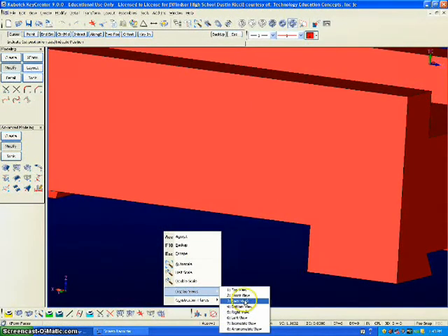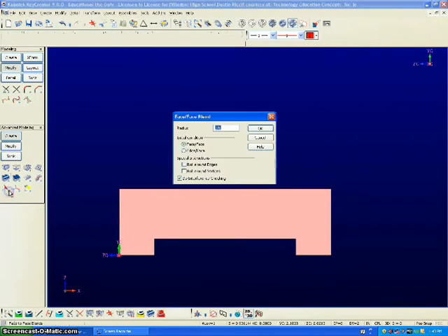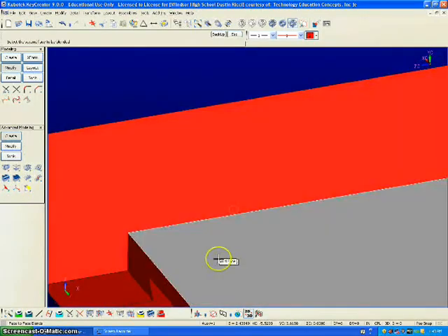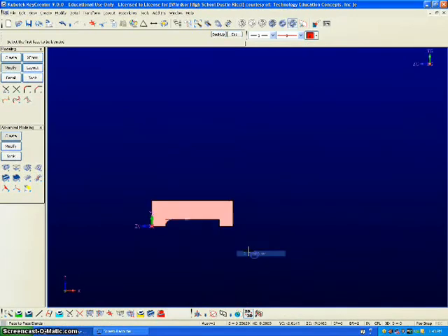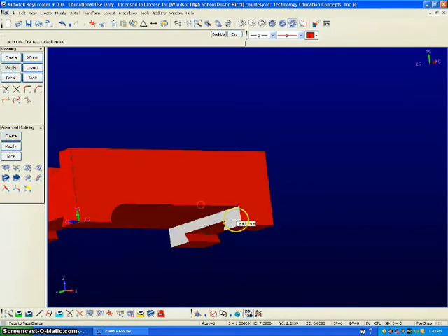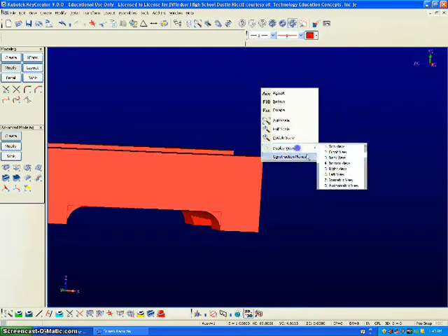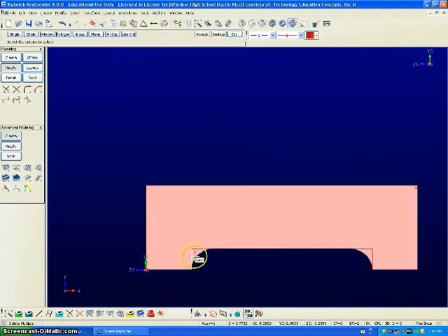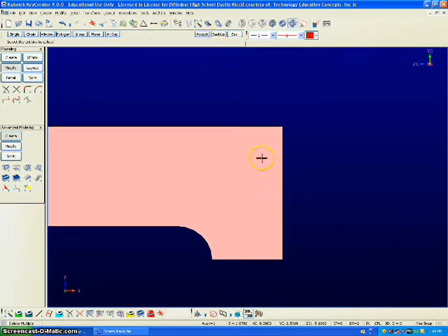We're going to go back to the front face now and give these a little blend. So create solid blend, face to face blends, radius 0.5. OK. I'm going to click the side face here, top face. Go back to the front view, side face and top, and that's done. Now we're just going to get those lines out of the way so we won't have to worry about them later. Delete multiple, and the 3 trimming lines that we made earlier, they're gone.